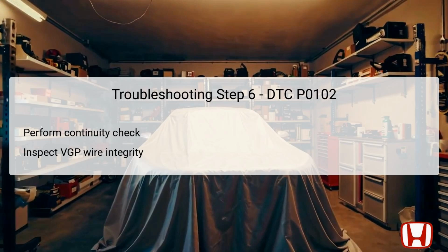As in Step 5, you will check for continuity between test points 1 and 2, where test point 1 corresponds to the ECM connector B, number 22, LT blue wire, and test point 2 corresponds to the MAF sensor, IAT sensor, connector number 5, LT blue wire.